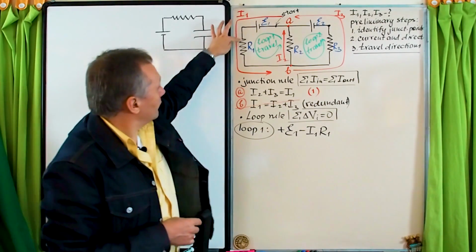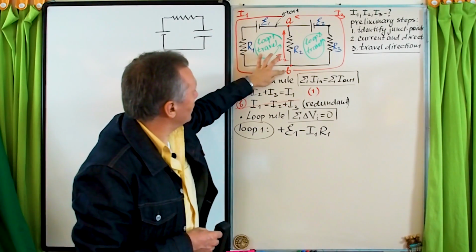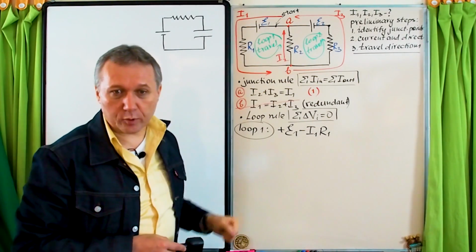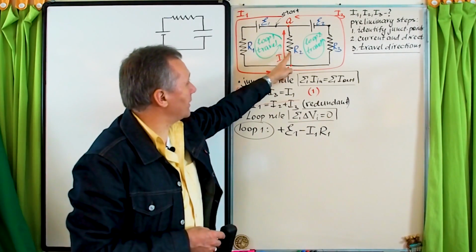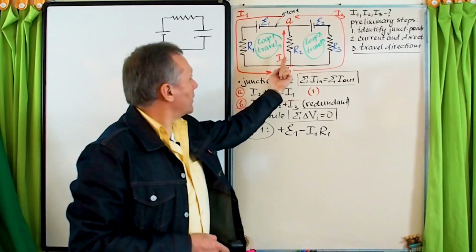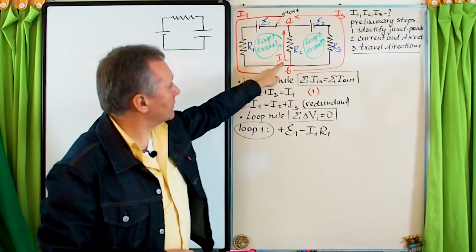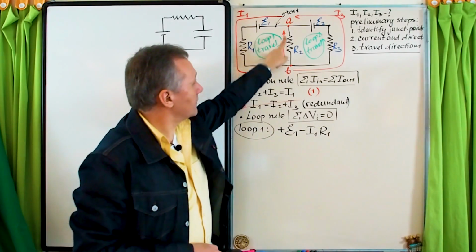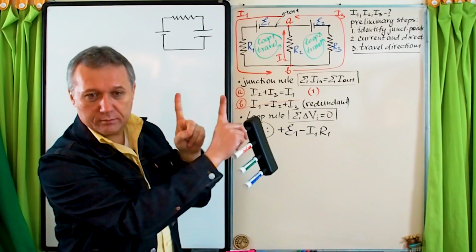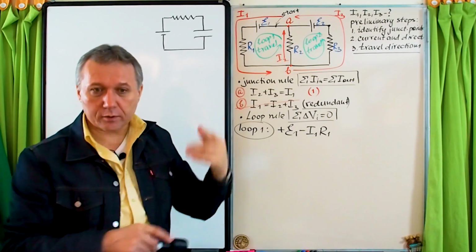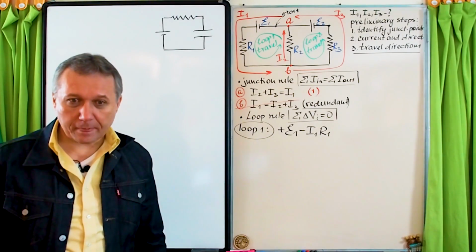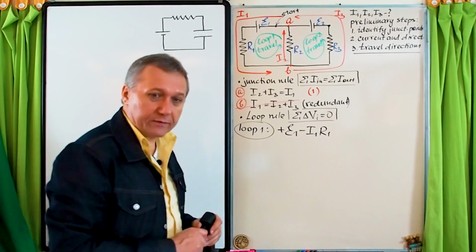Then we pass this. Now we have to go here, and up through this small bridge. So now we're up against this resistor R2. Let's look at the directions. Current now is I2. Current is up, travel is also up, the same directions. Again, the same rule number 3, which you have in your notes. So the contribution will be negative, minus